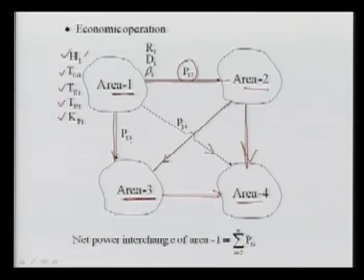We also have some other parameters in this area 1, that is R, the regulation. We have the load, that is the frequency dependent load, related with the constant D1, and that is related to the bias factor B1, because they are related here. B is nothing but D plus 1 upon R. So if they change, this will also change.